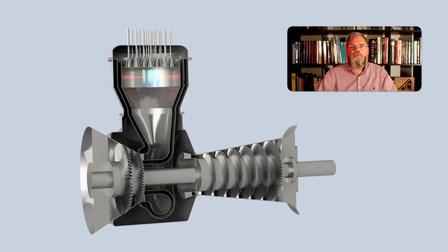The air from the burners which are switched off then mixes downstream with the hot exhaust gases from the burners which are still on to reduce the temperature down to the required turbine inlet temperature. This concept works well, allowing premixed burners to be maintained down to idle, but it has a number of problems associated with it. To understand this, let's now consider how the flame is stabilized in a premixed burner.